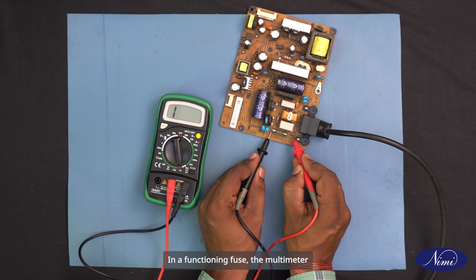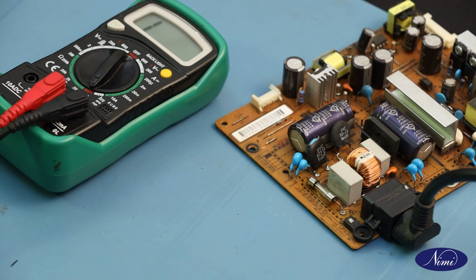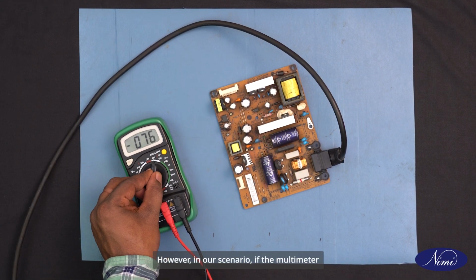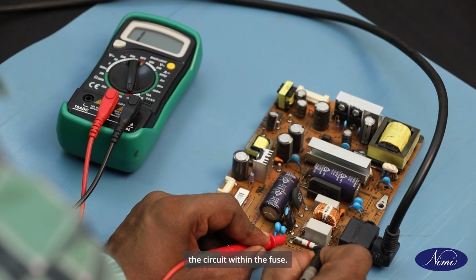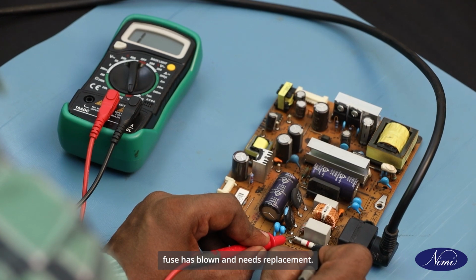In a functioning fuse, the multimeter should register a change from 1 to 0 accompanied by a beeping sound indicating continuity. However, in our scenario, if the multimeter continues to display 1 without any sound, it signifies a break in the circuit within the fuse. This condition confirms that the fuse has blown and needs replacement.